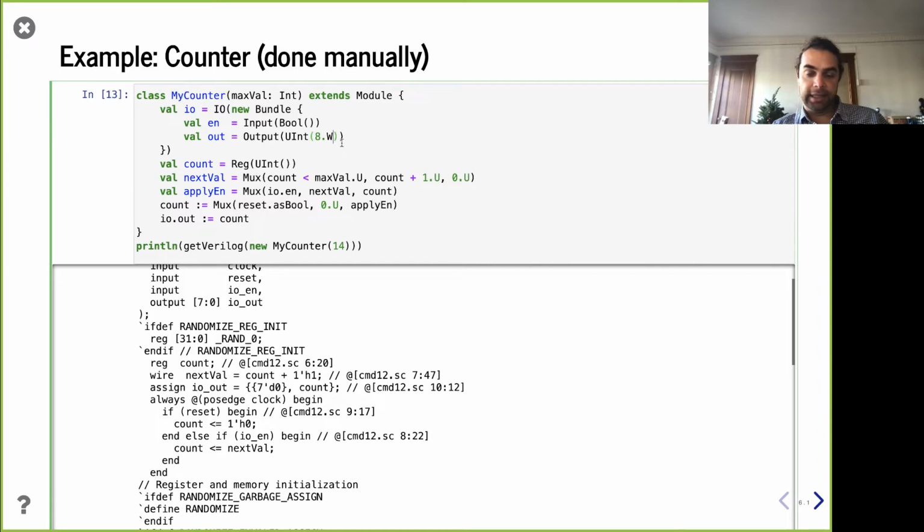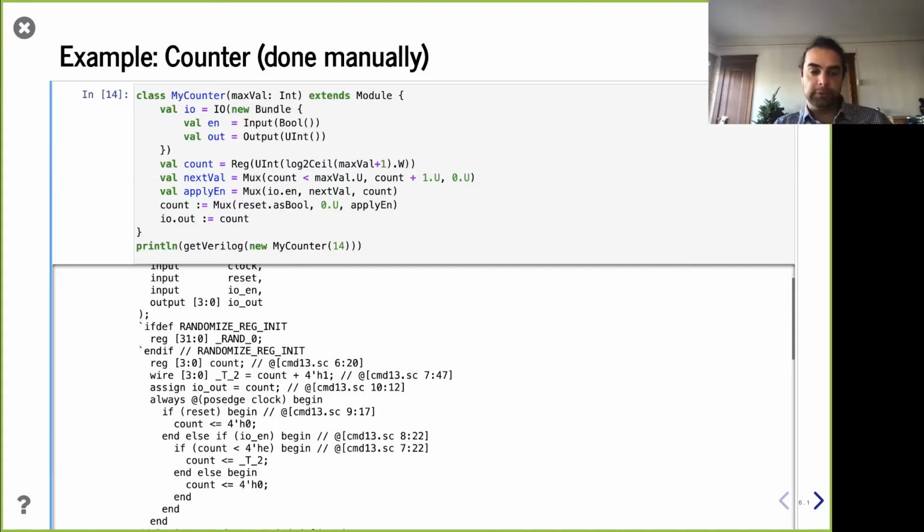But I argue it's better to choose to set that width ourselves, right? This is one of those cases where we're doing a little bit of width calculation on our own, but from a code point of view, it's done, I would argue, in a very safe way, where we're doing it only in one place, and then the rest of the widths in our design are going to be inferred based on that. So I think this is kind of a graceful, elegant use of that.